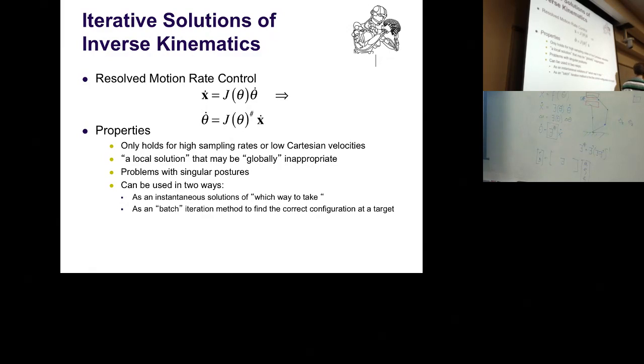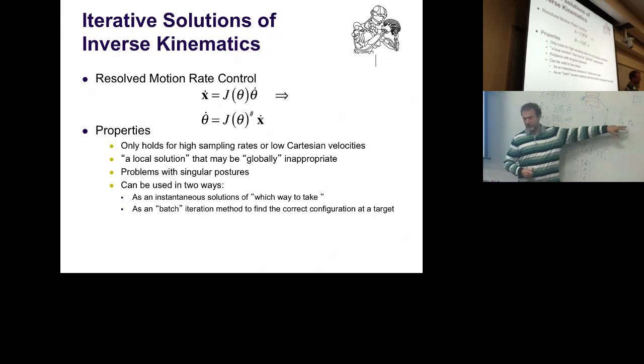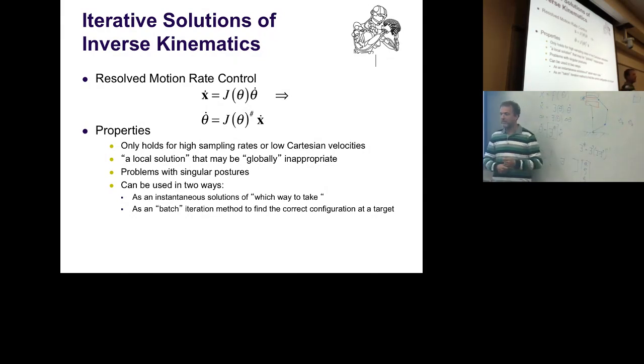Yes? So if we want to make it a straight path, we split the steps into small pieces, do one step at a time and realize it with a robot. But if you compute everything beforehand, then you only have the start and the end joint angle configuration. That doesn't tell you how to go on a straight line in end effector space to the target. Okay? So it's sometimes nice to just compute everything in simulation and execute it in a particular way. It may be energetically better, but it may be workspace-wise inappropriate. You notice this is the fun thing. We go back and forth, workspace, joint space, workspace, joint space.